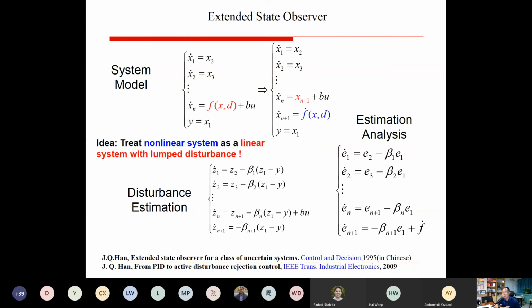the nonlinear control may sometimes not have enough advantage over the linear one because of the saturation situation. If in the working condition you always meet saturation, then everything is the same. For example, the open loop, the PID, and the nonlinear control: if they are in saturation most of the time, half of the time, then there is no difference. But outside of the control saturation stage, the nonlinear control should be better than the PID. So the advantage depends on the control saturation status. If it lasts long, maybe there's little difference. So in this way, we should suggest the designer have good enough hardware, to give the control algorithm a good place to show its potential and show a better result. Thank you very much. That's my answer. Yeah, thank you very much for your answer.